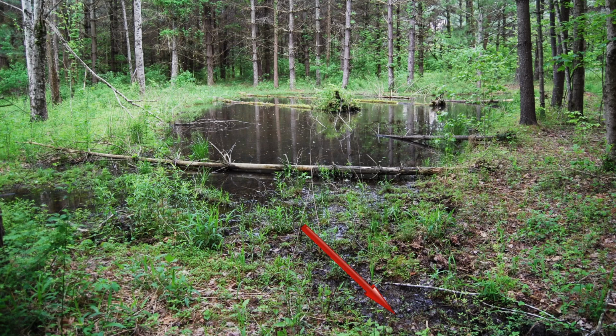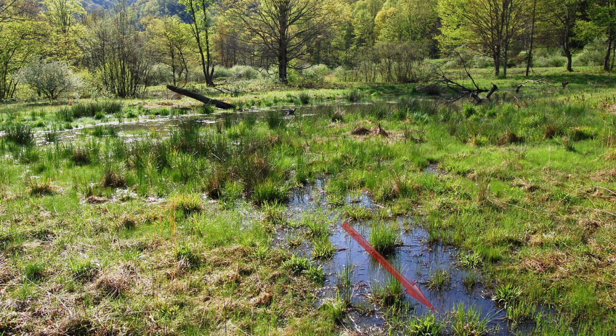The arrow shows another spillway for a wetland. One can locate the spillway by walking around the wetland and looking for where water is flowing out of the wetland. The spillway often looks like a bay or an extension of the wetland. One can watch for a flow of water to see where water is leaving the wetland. Sometimes it's necessary to place leaves in the spillway or to muddy up the water with your foot to see where water is flowing out of the wetland.